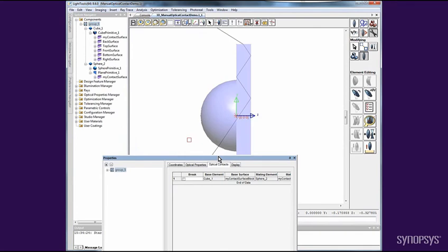In this video, we explained the importance of optical contacts to achieve realistic ray tracing and simulation results. We then showed a way for LightTools to automatically set the optical contact relationships using Auto-Declare Contacts, and then how to set the optical contacts manually.